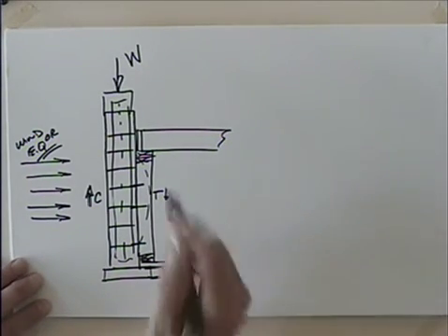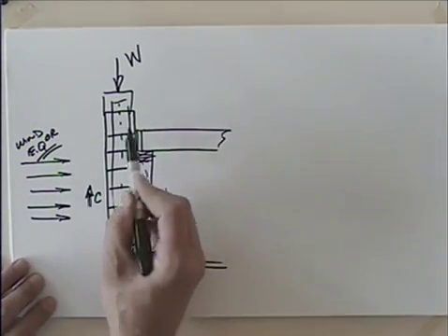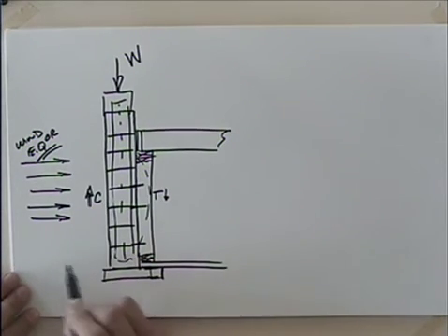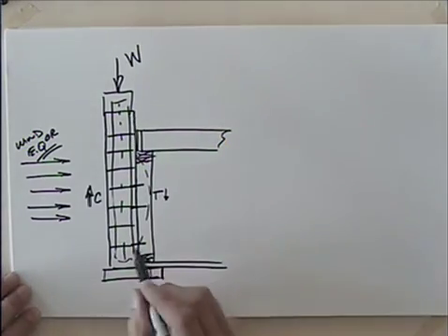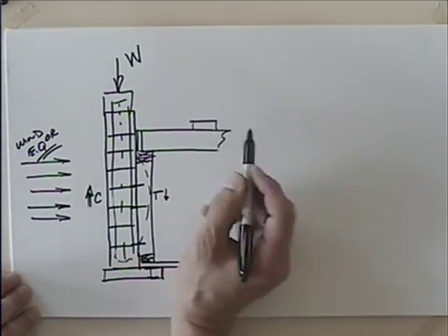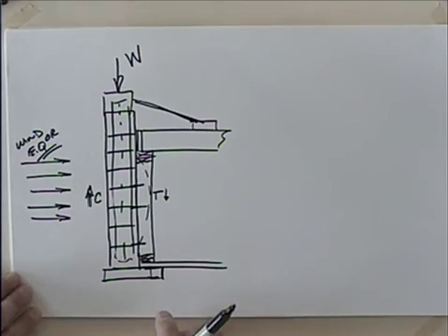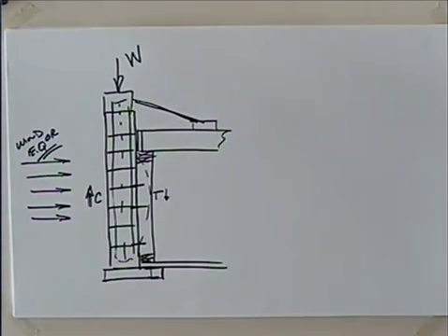Okay, and then the parapet is really a death wish. So if you look at after they've had an earthquake or something, and there's rubble on the ground, and you wonder where did it come from? Well, it's probably the parapet that fell off. So that's always falling off on people or cars. So if you want to do structural retrofit, you're going to come up here and probably put some bracing to that parapet, because this parapet shaking around at the top of the building is a real problem.